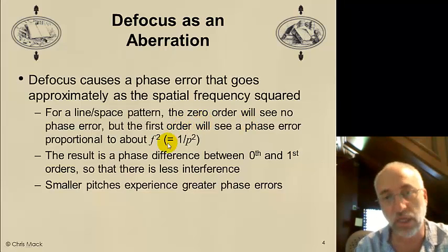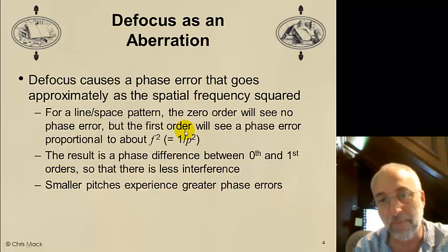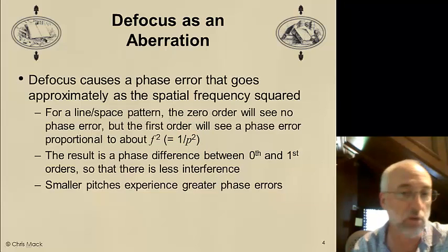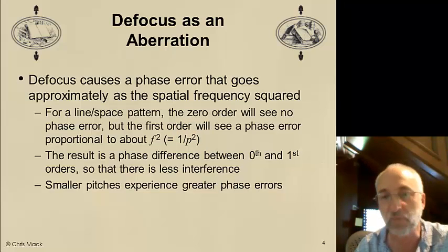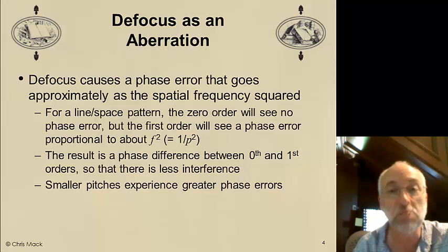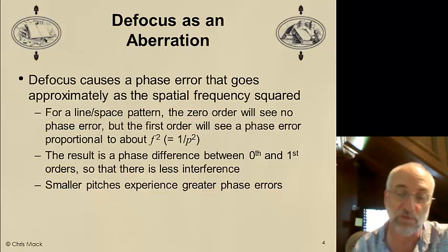We also see that the amount of phase error is proportional to 1 over the pitch squared. So smaller pitches experience greater phase errors. This will be very important. Large features experience the effect of defocus much less than small features do.